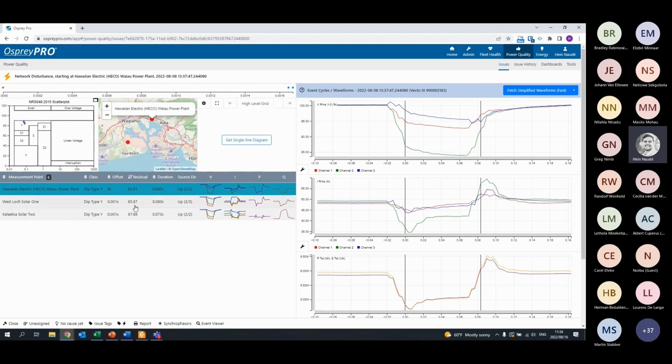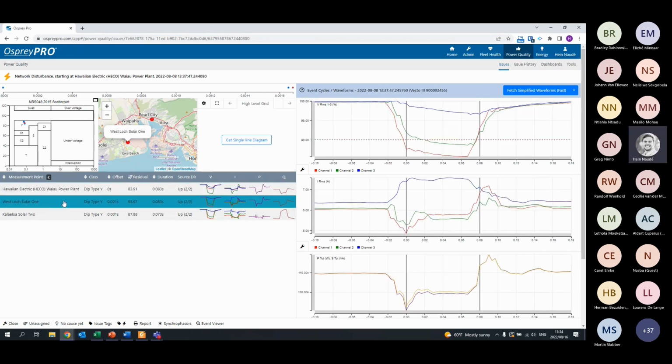And then if you click on a specific one of the meter points, you can actually get more information on the right. So this is what I was referring to earlier on one of the questions, that you have your RMS voltage. So here's the dip. It looks like a line-to-line fault that may have happened, causing the 2 phases to dip on red and green. But you can also compare your RMS current on the same page without needing to plot a trend. It's immediately here for you.